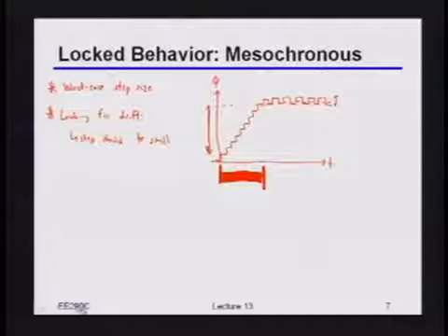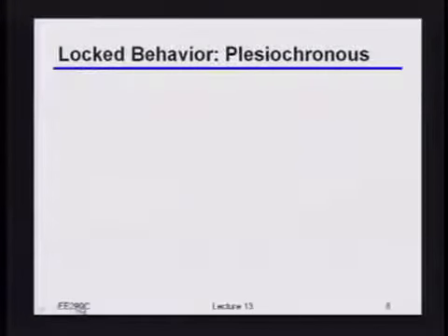Okay, so this was all for a mesosynchronous system, where the trick was, I said, the two clock frequencies are the same, but the phases might be slowly drifting relative to each other, okay? But remember, especially, for example, in your project, in many systems, you don't have a mesosynchronous system, you don't have the same frequency, you actually have frequency offsets between the two sides, okay?